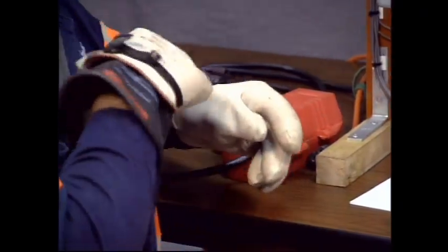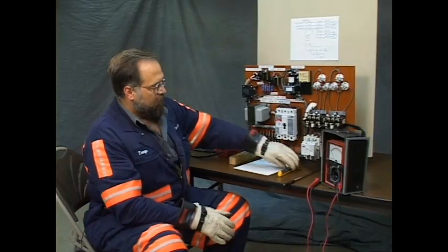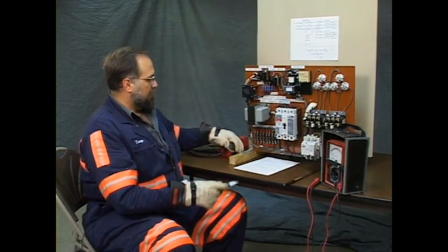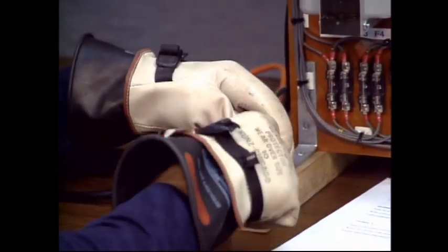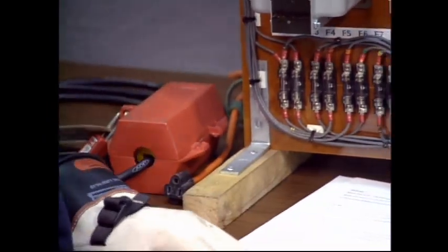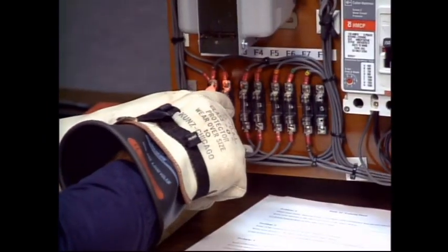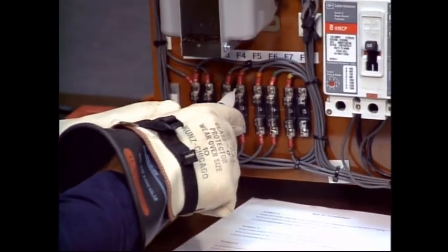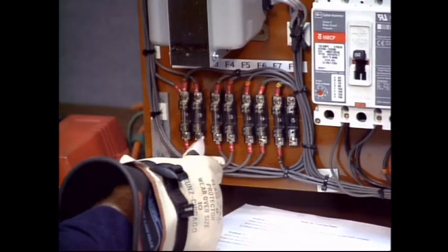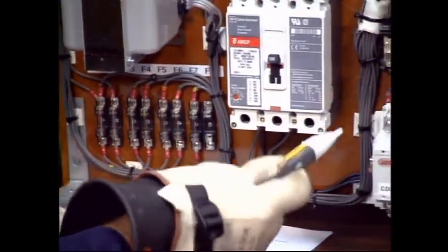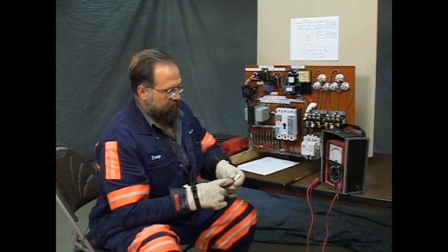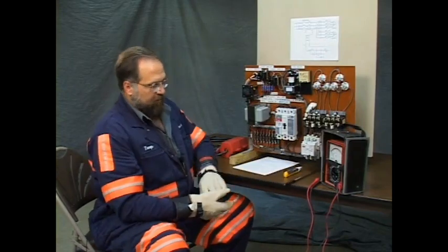We're going to stow the key. Now we're going to check for voltage to make sure that indeed the power is off. I'm going to check on a known live circuit. And I have power there. My voltage tester is operational. Now let's see if we have any power on the board. There's no power indicated. I believe we're good to go. We can take the gloves off